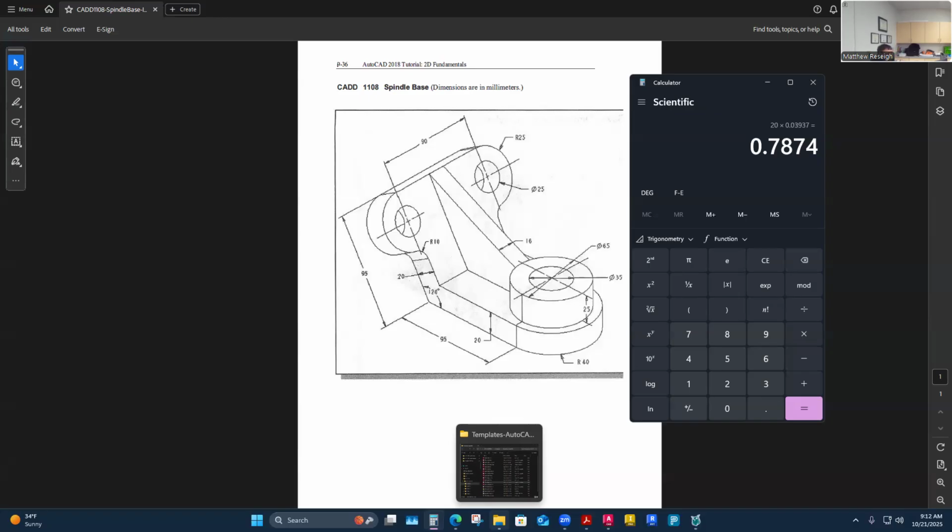I like to think through how these processes were made. This is potentially three different parts. If this was made out of metal, it would be a very hard bend to pull off and have the accurate measurements fall out. It would take some experience to figure out what my equipment does. Or maybe I'm going to miter cut this like you would with wood, saw cut those bevels, and then have a welder join them. That's a total way this could be done.